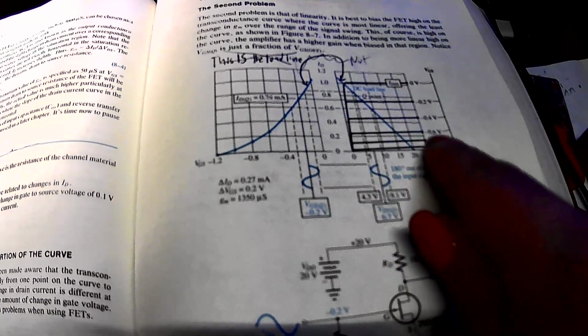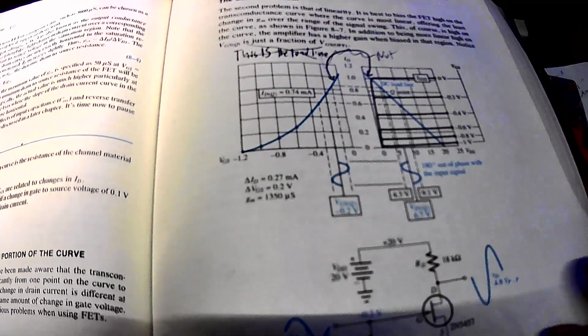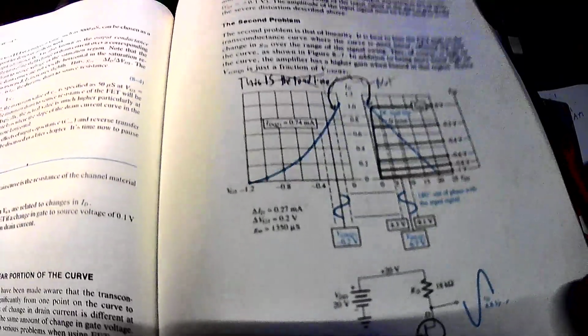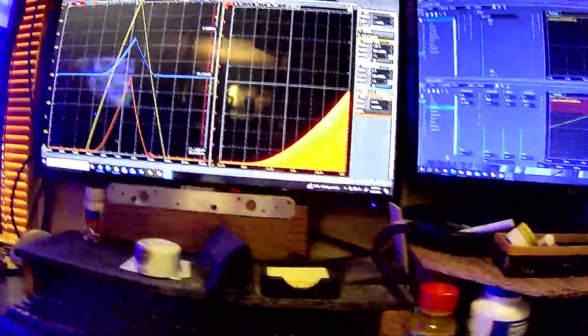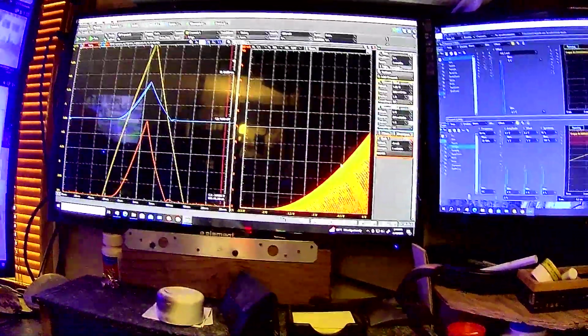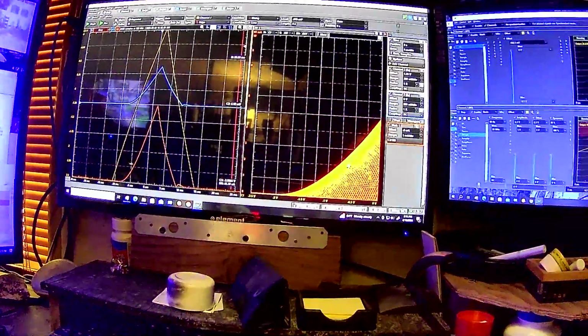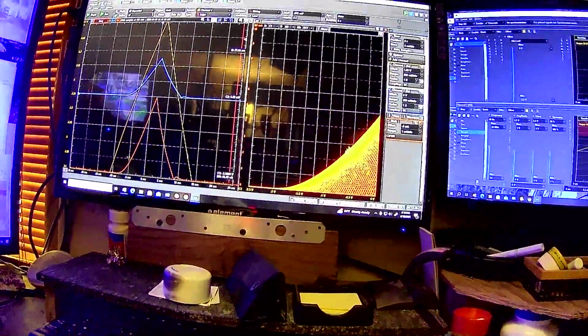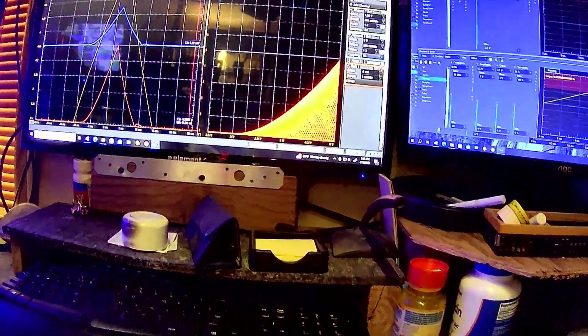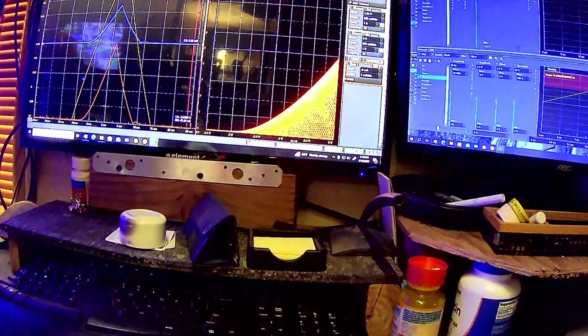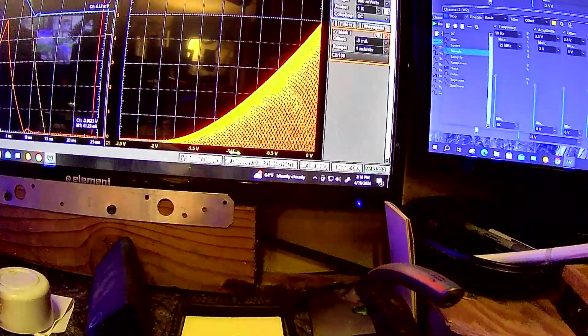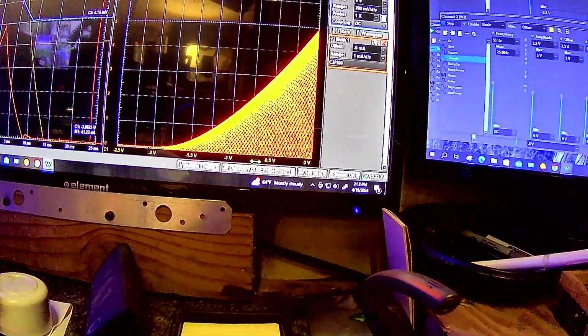And of course, I can't generate this because the voltage doesn't go high enough on this Analog Discovery, especially to do sweeps on the drain source voltage, etc. But at any rate, it's a convenient arrangement. So if you've got yourself an Analog Discovery and you want to test JFETs, since its transistor tester doesn't have that built into it, it's a way you can go about it. But again, you have to estimate it kind of the same way he was doing there. It's a shame you don't have cursors here, so I can't get a direct reading on this. I guess that's like half a volt there and minus 1 volt, so it's about 0.5 volts change.